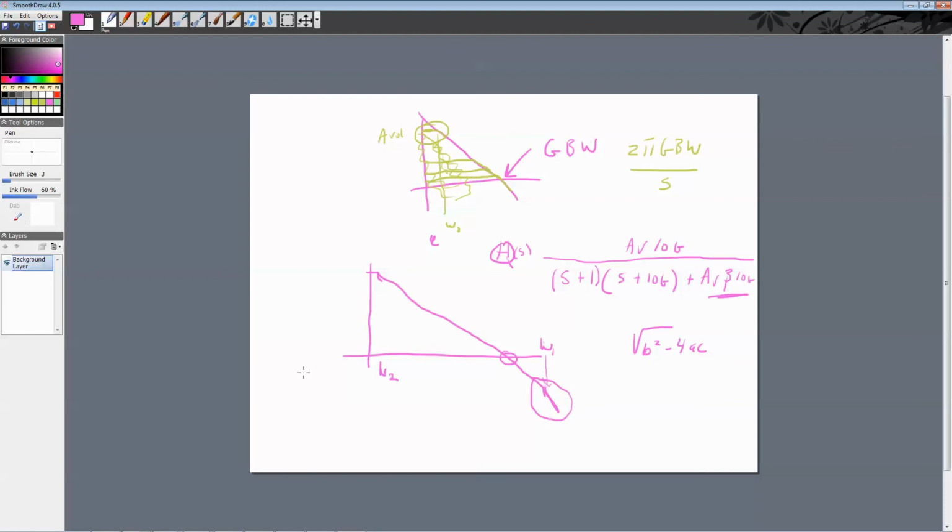And beta, if it's a buffer, beta's 1, that's as big as it can be. And so the gain would come out, but this would be the actual filter. I'm not saying it happens right there, but you could get a Bode plot that looks like that. We haven't gone over it that much, but a Bode plot that has this peak has complex roots, and it will have some underdamping.